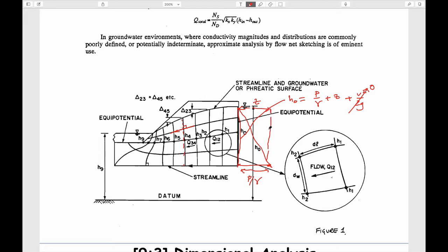And so indeed the sum of pressure plus elevation, which is this, is equal to a constant value on this boundary. It's equal to a constant value on this boundary here, because it's in a lake, from the same idea that if you go down a swimming pool, the total potential head, H, is constant. As you go down deeper, the pressure increases, but the elevation goes down.